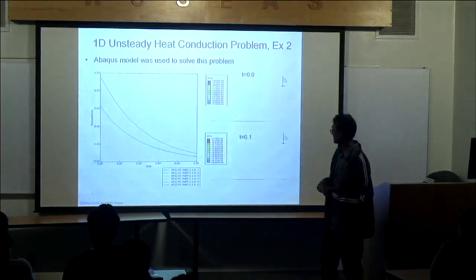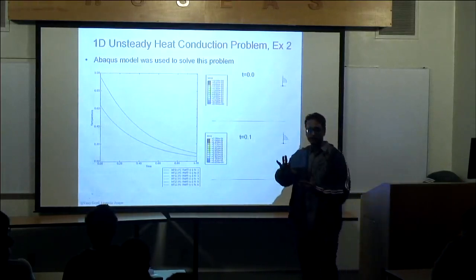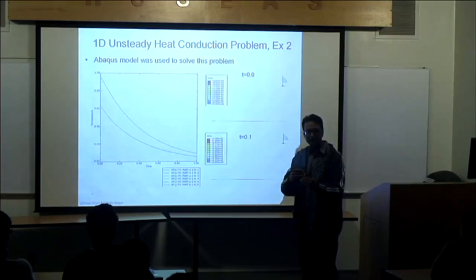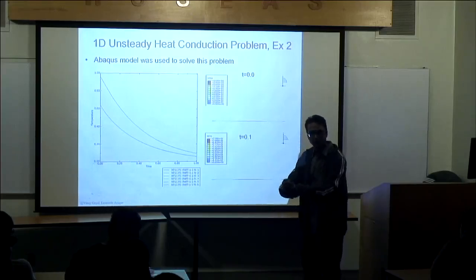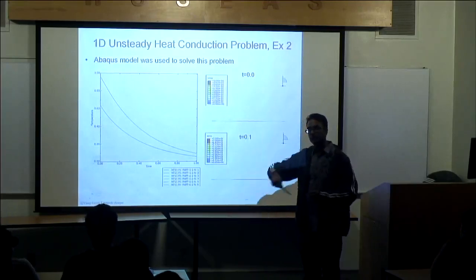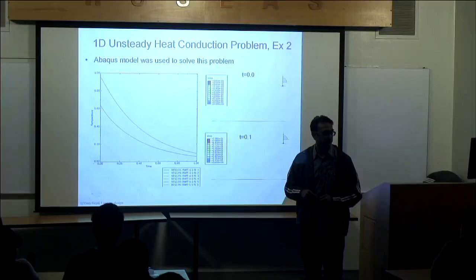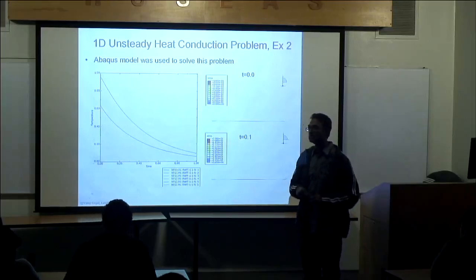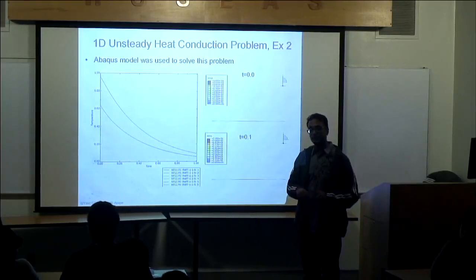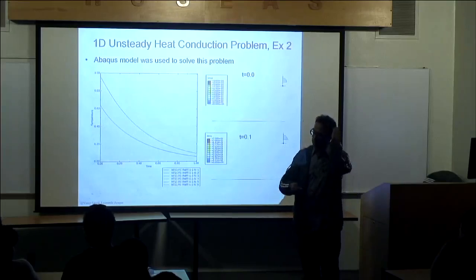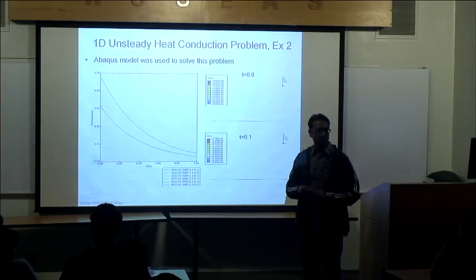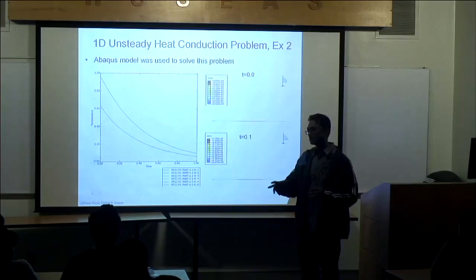In fact, in this particular problem, I did this on purpose. If I had continued this time step of 0.1, although at the beginning it kind of looked right, the lesson learned that I'm trying to give you here is that I used explicit integration, remember? If I continue marching the solution, it will go unstable. It will give you non-physical results that don't make any sense. Because the explicit time difference scheme requires a conditional time step to be stable. I gave you the formula: it's 2 over lambda, where lambda is the max eigenvalue.